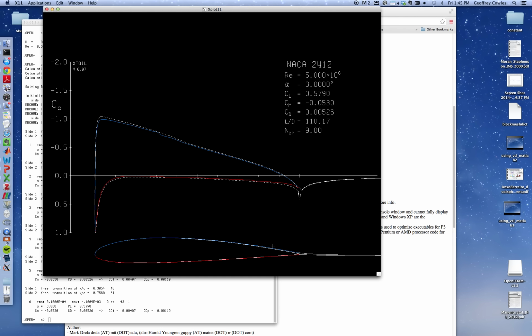And this shows you the airfoil. So effectively it displaces out the airfoil due to the thickness of the boundary layer, which influences the pressure distribution here. So the fact that the boundary layer itself has thickness changes the apparent shape of the airfoil to the free stream flow and influences the pressure distribution a little bit. We could rerun this as an inviscid foil and see how much different the lift is at this given angle of attack, and that might be an interesting exercise, but we'll skip that for now.